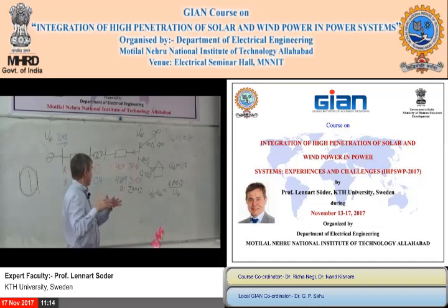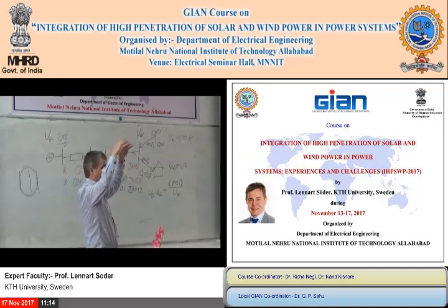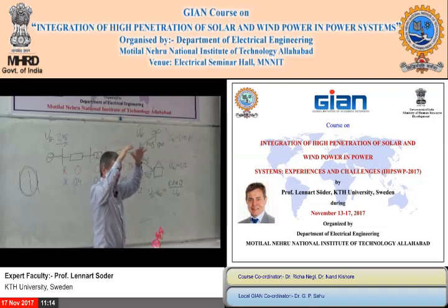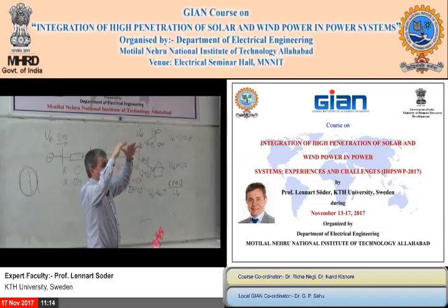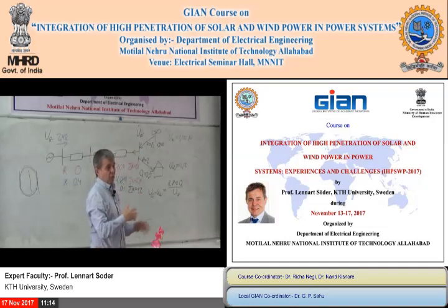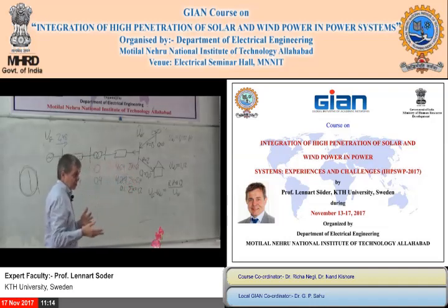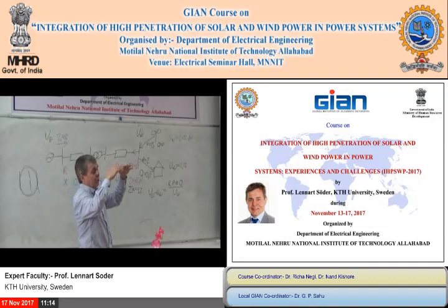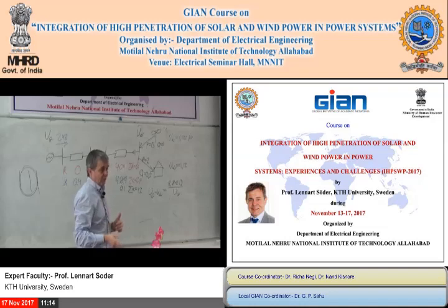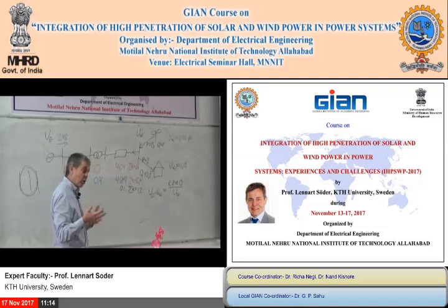Then you come into the other part, for both wind power and solar power. What you normally do in solar and wind power is that you keep as much production as possible. In solar power, you have MPPT, which maximizes the amount of power. Always, because why should you not get as much as possible? And then, of course, what you always can do is, okay, too high frequency, we decrease. So 50% of the primary control, of course, you can do. If it's too high frequency, we just curtail the wind power or solar power. If you're on the maximum, you cannot increase, of course, but you can always decrease. So 50% of the frequency problems you can manage, and you can partly participate.